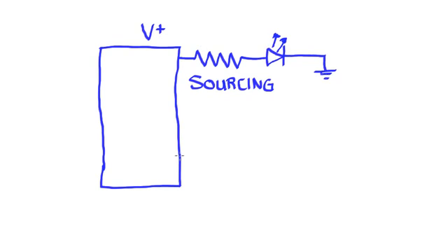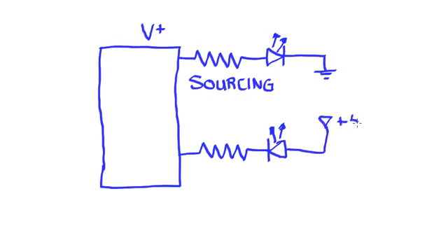Now we can also take a pin or a port, connect up an identical resistor and LED, but this time put the cathode end facing the microcontroller, and that would mean that the anode end would need to be connected to our positive end of our power supply. Let's say in this case positive 5 volts.